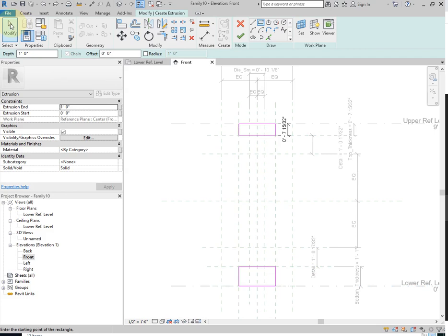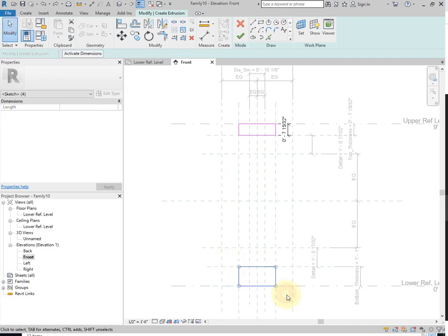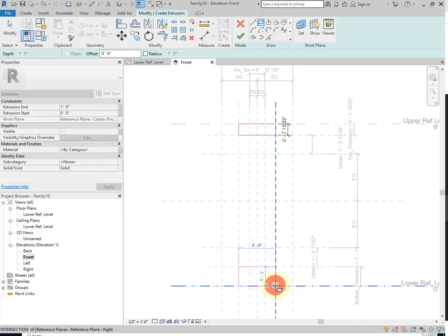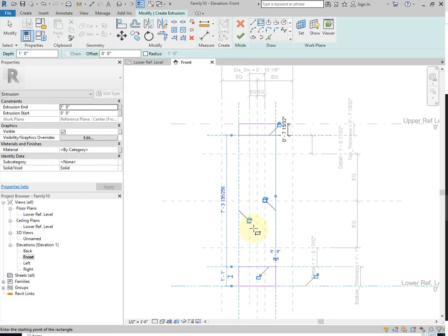So when I did that, I want to make a note here where that lock is. I don't know if you can see, we got a padlock and an unlocked padlock on top of each other. So when I hover over that, I'm making sure I have the gold padlock highlighted before I click it. So I don't want to unlock the other one. I want to lock this one that's unlocked right now, so it stays connected to that reference line when it moves.